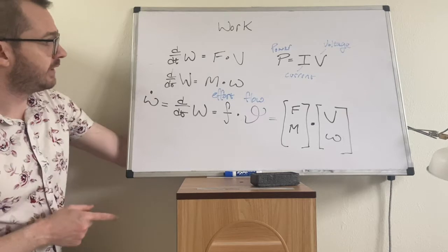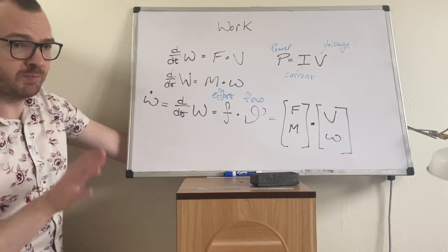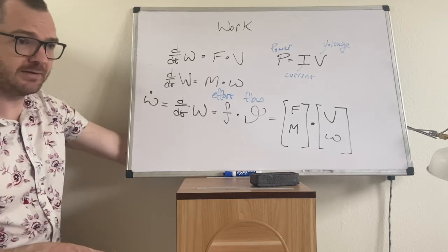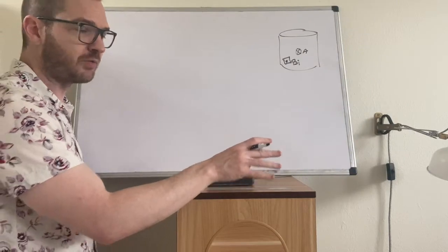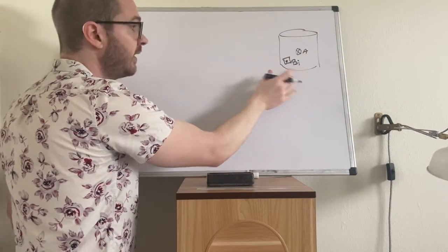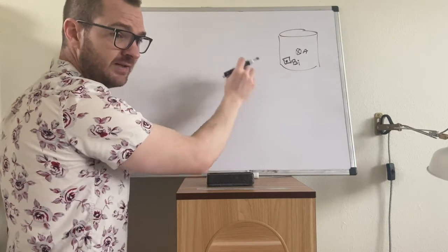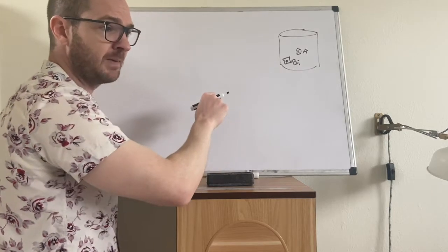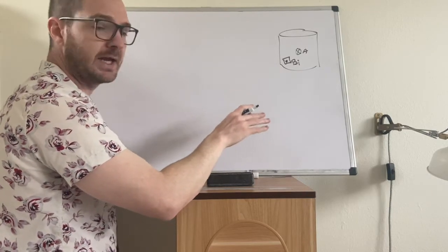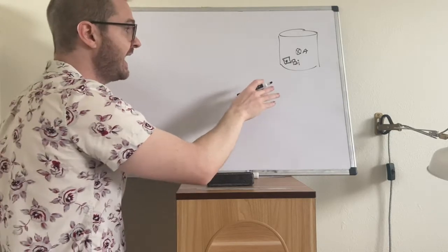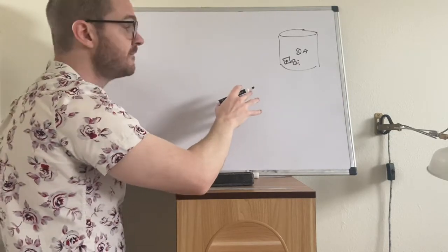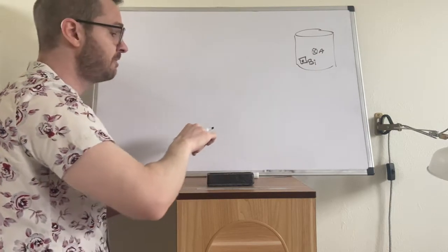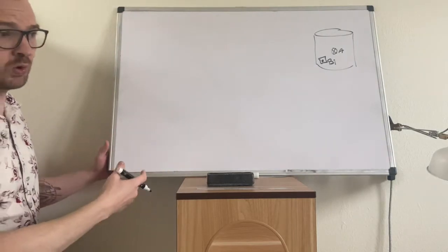So where we need to go next, I'm going to clean this up, and let's go back to the original definition of work, and let's talk about how we can use work to now calculate kinetic energy. I've drawn a rigid body with known center of mass A, and we're going to discretize this rigid body into infinitely many small differential bits of mass. We're going to track those with the point B sub I. We ultimately want to find the kinetic energy of the rigid body A, and the body A can both translate and rotate. Let's begin though by finding the kinetic energy of just that differential bit of mass, B sub I. And let's start with the equation for work.